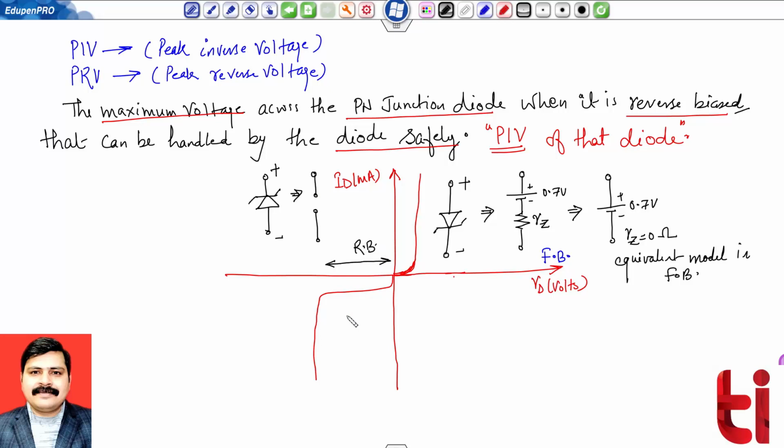So this is forward bias, this is reverse bias, because after that this particular term is my Zener region, and this voltage is Vz, which is my Zener voltage. Functionality of diode in this Zener region will also be same, and the behavior will be like this.